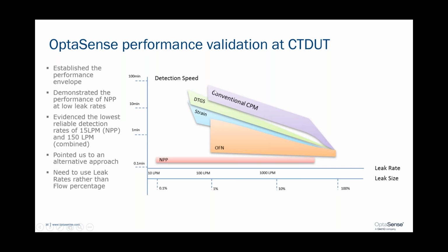And this is where we've tried to show how the computational CPM approach works. Different gatings for different window sizes. So for ruptures, it'll trigger in tens of seconds or minutes, but for the smaller leaks, the 1% or so, it's tens of minutes. And I've overlaid on here where our 4 modes have their applicability.